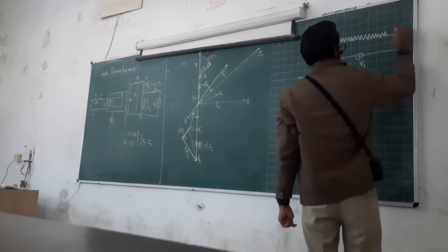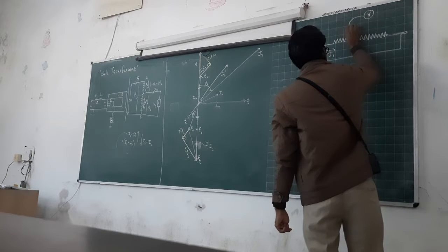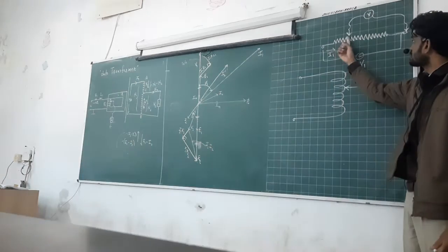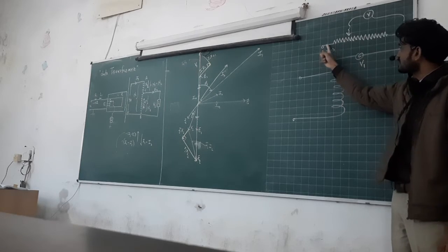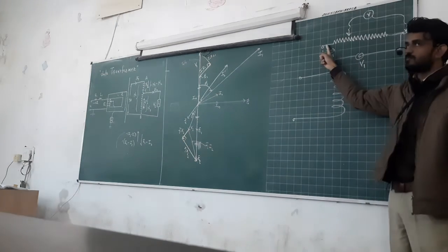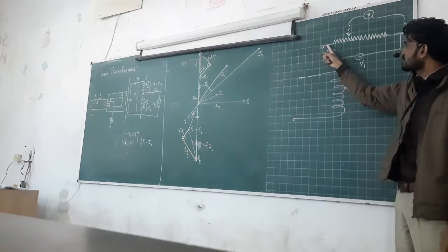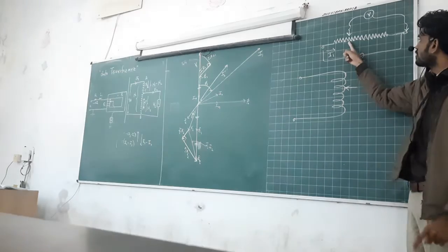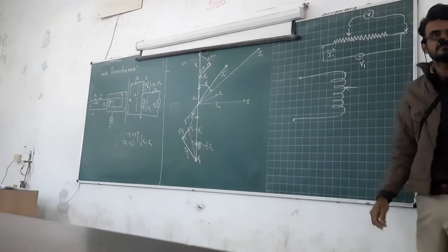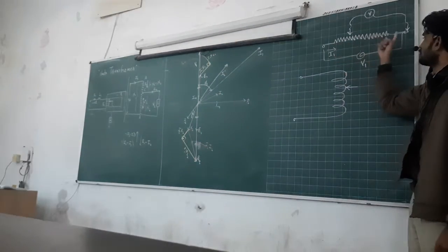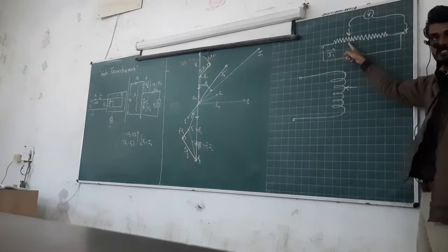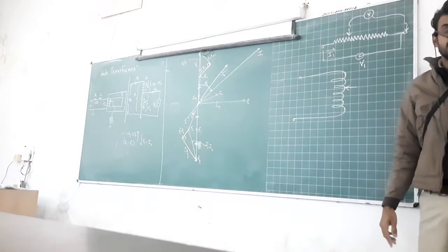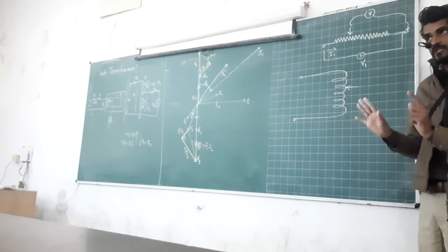But now if I take a voltmeter, and connect one wire here and another wire here, then I shift this point. If this point is here, then the voltmeter will say voltage V1, let's say 100 volt. Then if I shift the voltmeter point in this direction, it will only read the voltage between this portion and that portion, and that voltage is lesser than the full voltage. So here is 100 volt, here 90, 50, 40, 30, 10, 0 volt. In this way the voltage divides across the resistor.